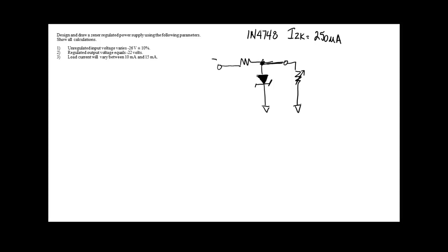By the way, when you make copies, you lose that decimal point. So if you ever see in these data sheets a leading 0, then you know there's a decimal point right there. You see when I write them up here, I start mine with a 0 too. It doesn't say 0.25 milli. Okay, so 0.25 milli is 250 micro. Understand, Kareem?